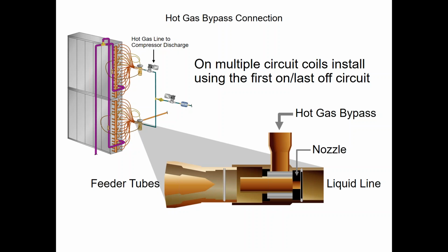And basically we have oil ports through the compressor that lubricate the bearings and the lobes of the screws. So not all compressors have oil that sits in them, but all refrigeration systems have the oil moving through it via entrainment with the refrigerant.